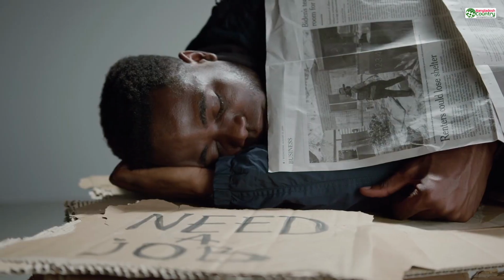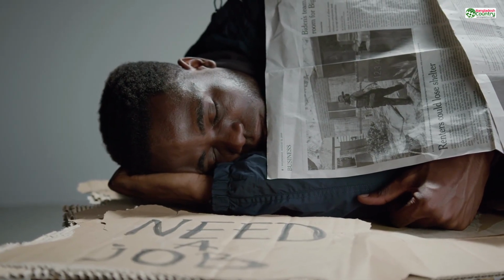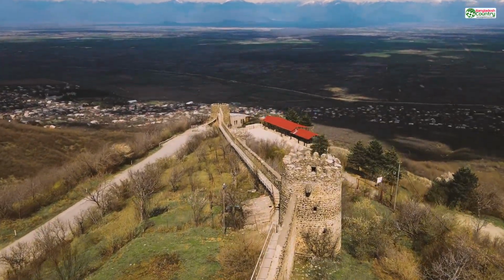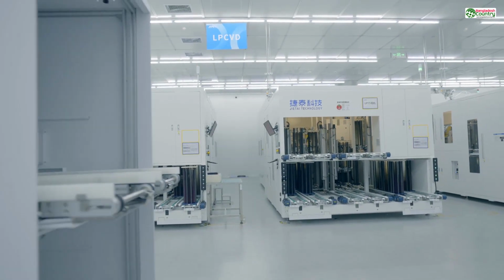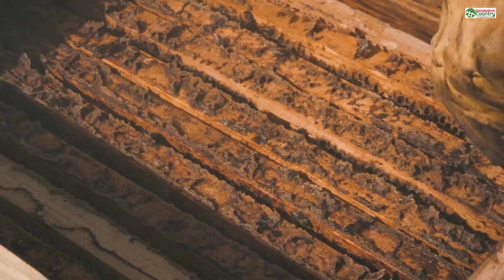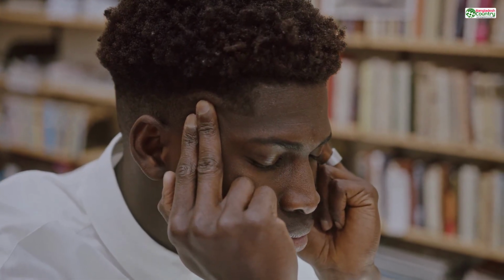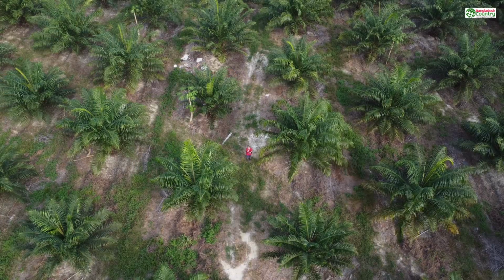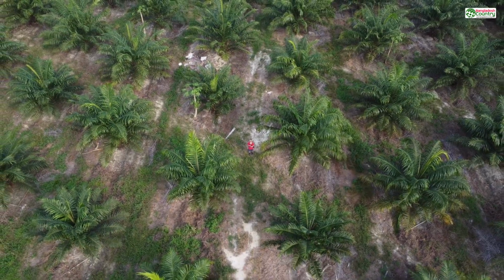The answer is to think like an architect or an engineer. You don't make a solid wall. You reinforce it from the inside. Most advanced 3D modeling software allows you to add an internal lattice structure or a honeycomb infill inside your hollow model. Think of it like the rebar in concrete or the wooden trusses inside a wall. This internal scaffolding uses a tiny amount of material, but provides immense structural rigidity across the entire part. It prevents the large, flat walls of your hollow model from warping or buckling.